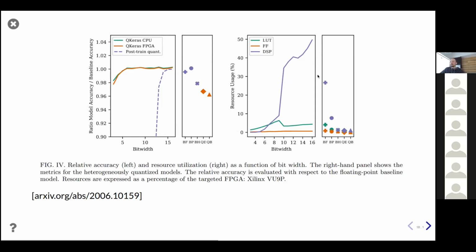And here also, interestingly, you assume a variable bit width representation. So we're really looking at how our model will behave with a particular bit width representation. We're moving away from these fixed steps of having only available, for example, integer 8, and we look at integer n representations instead.